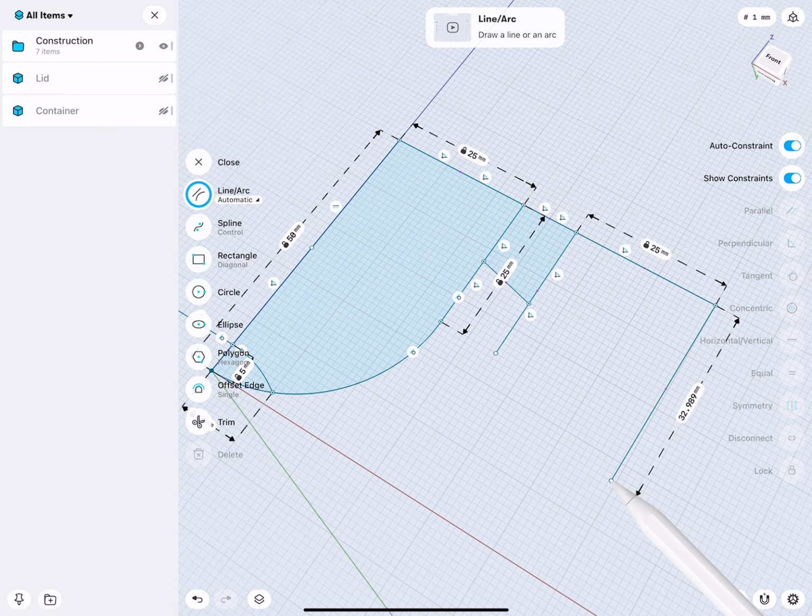So this, as you will see, fits perfectly in there. And this line, I would like to do an offset down, maybe to there. Very good. And then I can extend, for example, these points a little bit. Let's add a distance to there, 35. So it's a little bit over the arced areas, not only on the flat lines. If we want to center the line here, make a vertical line, and then we set this vertical. Very nice.